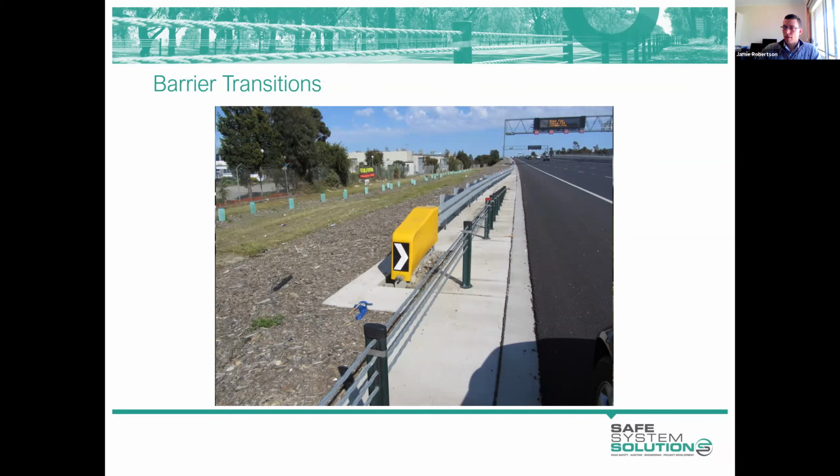Now, there is an argument that you're unlikely to see a deflection in that order so close to the anchor point, and that's probably true. But the conservative way to do this would be to locate this guard fence at least beyond the deflection area of this wire rope in front.